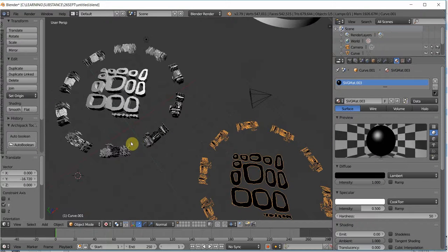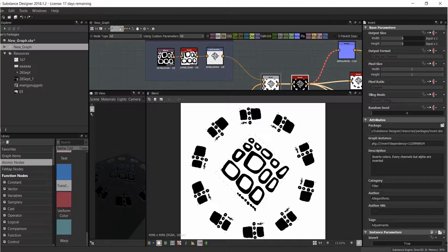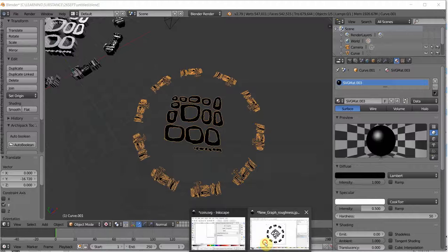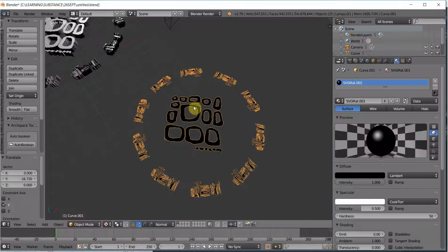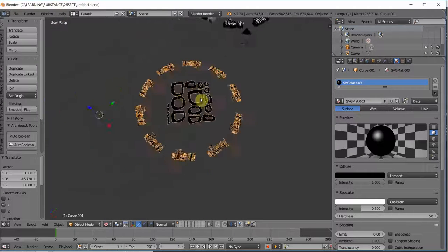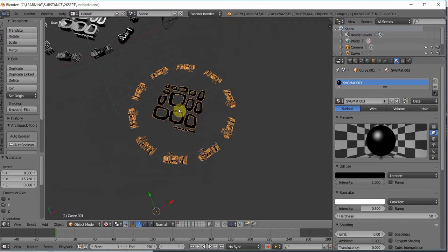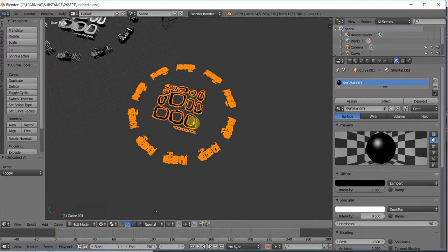And then we've got the cool design, which isn't the design from that one, it's the other. Yeah, if I'd saved that, it would be this more blocky design, which is much better for 3D printing, by the way, but this is the original design, which is very thin, which isn't so good. So I'm going to change it to the blocks. And then I go to edit mode. I select all. E to extrude.